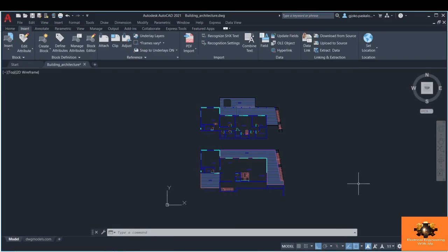Okay guys, in this lecture we are going to talk about external references, or in short, XREFs. External references in one way allow us to use multiple drawings on the same project and communicate with the data of those drawings. One powerful feature is that the project file size doesn't increase with the additional external drawings. So we are able to work on large projects and still manage to save some memory. But the most powerful feature is that we can share the data and allow multiple teams to work on different phases of the project, and all that at the same time.